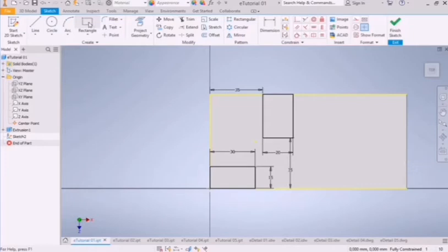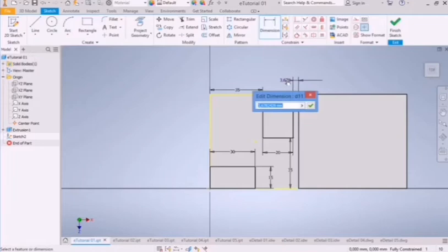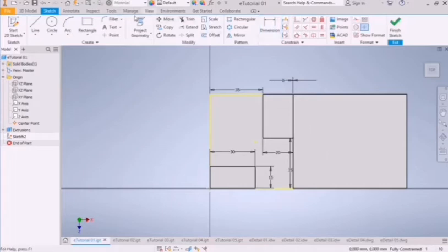So what we need to do is to join another rectangle from here straight from this point. Okay, let's do this in order to make sure that we are exact on, let's say, 0. Let's ground it there at 0, and then now we'll use our trim. Let's escape and then select our trim. We want to trim.